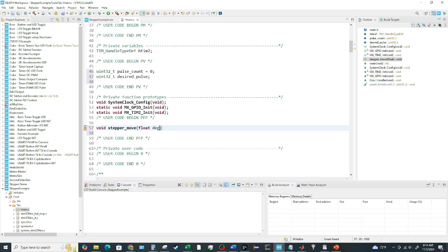And then, of course, at the very end, we're going to need to round to an integer number of pulses and an integer ARR register value. So we can do all this in float, and then we'll just have to round that to an integer at the end. We're going to command a number of degrees. We're going to command a speed, which can be defined however we want.